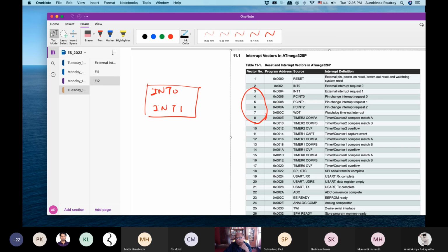In pin change interrupts, how many pins can you use? 4 each. You can use 24 pins. Any change in those will interrupt the processor. Now look at page 49 of this manual. Let me discuss a few things about interrupts. The external interrupts are associated with certain flags.